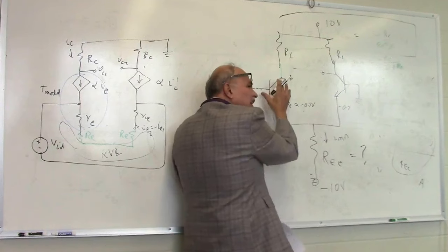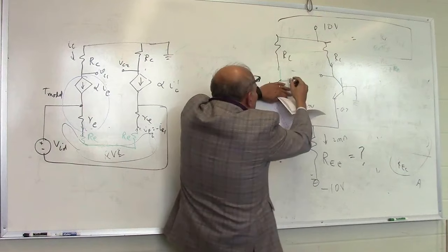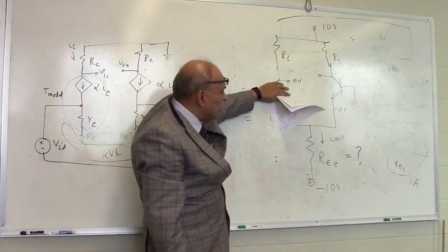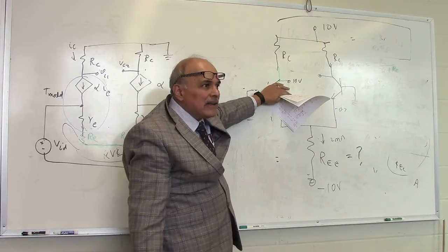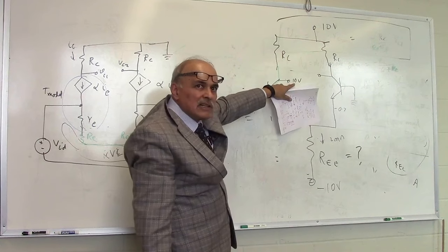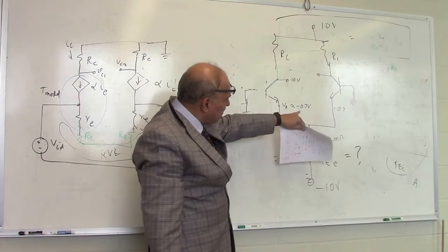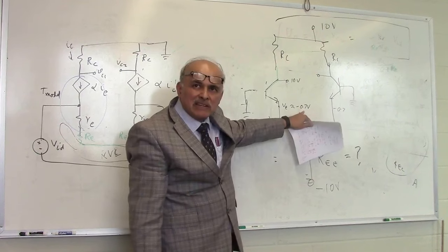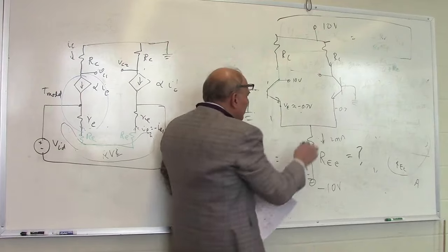And this transistor can operate between cutoff and saturation. When it's cut off, the voltage here is 10 volts. Correct? There's no current flowing, so output voltage is 10 volts. When this transistor is saturated, what will that voltage be? Oh, sorry, 0.2. Roughly 9.8, minus 0.5 maybe. Yeah, about 0.2 volts across here.